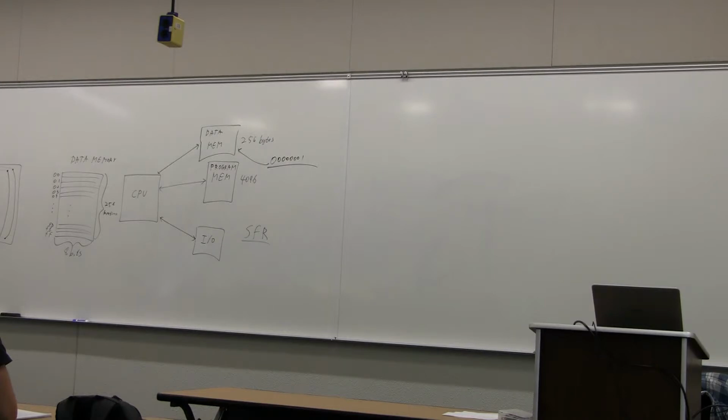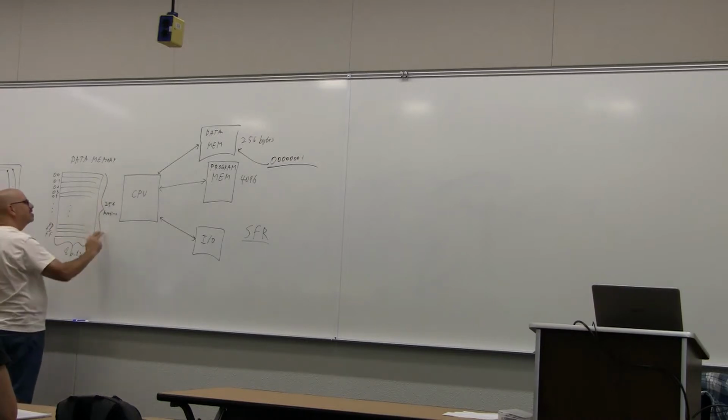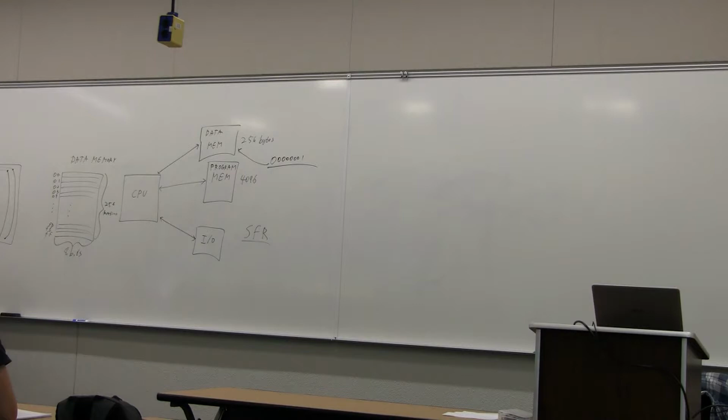And we tend to put leading zeros in front of hexadecimal numbers if we know we're talking about an 8-bit number, right? And we need 8 bits to specify one of 256 locations. So those are our hex addresses for our data memory. So 8 bits let us specify which piece of data we're interested in.